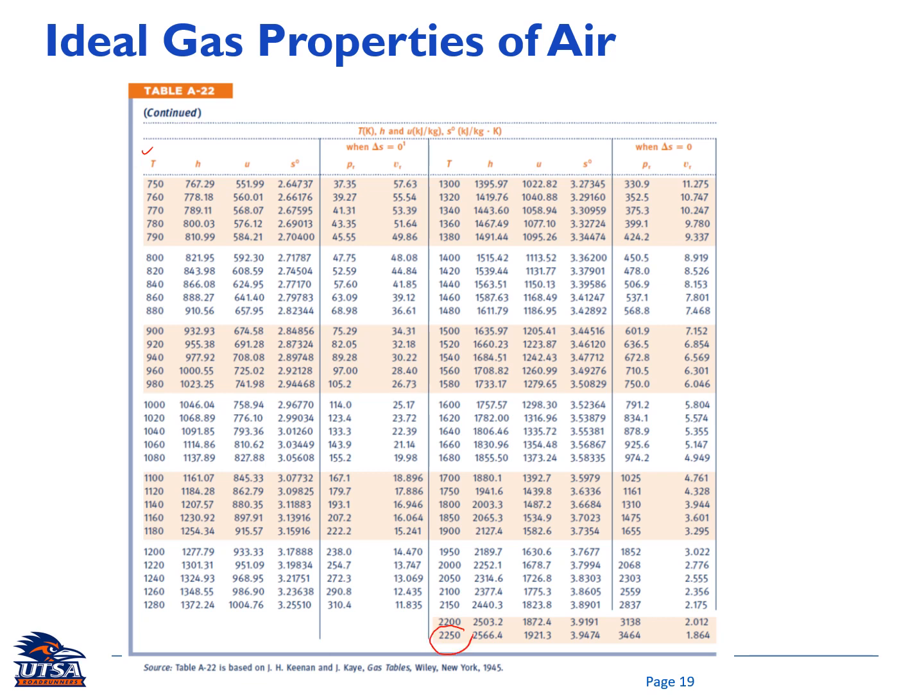As I mentioned previously, you have an SI unit type table, here table A22. And then you also have a British unit type table, with the addition of E in the name. So if you go to table A22E, you have a similar table, but under British units. The temperature will be in degrees Rankine, enthalpy will be in BTU, and so on.